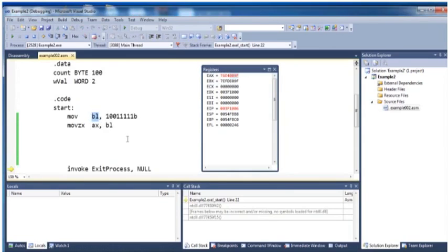Now for example, if we want to use the next value, if I say move AX comma 0101 hexadecimal. This is not 0101 in decimal, this is hexadecimal, and AX is 16 bits, so 4 digits can show 16 bits. Or maybe I can use FFFF in hexadecimal. What is the error here? The error is that if you're using any hexadecimal number whose starting digit is a character, you have to use 0 before it. So I will save this one.